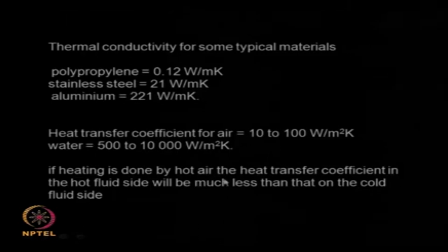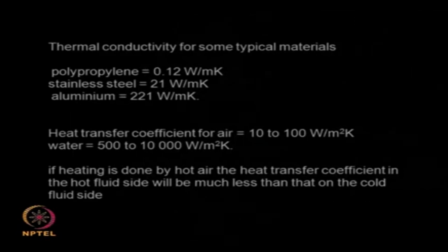So if the heating is done by hot air, the heat transfer coefficient in the hot fluid side will be much less than that on the cold fluid side, because the hot fluid side has air, cold fluid side may be having water or any liquid which has a higher heat transfer coefficient, whereas air is the worst heating medium, it has very low heat transfer coefficient.